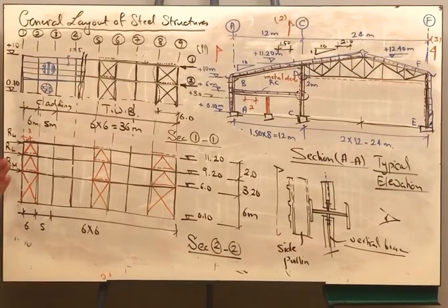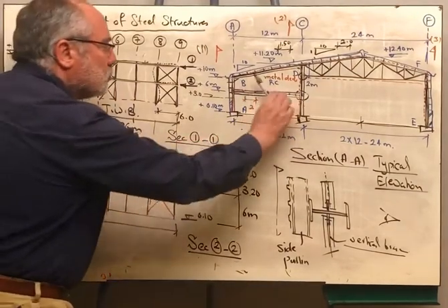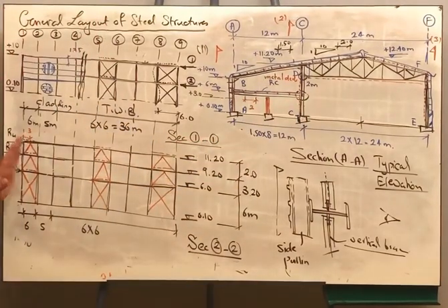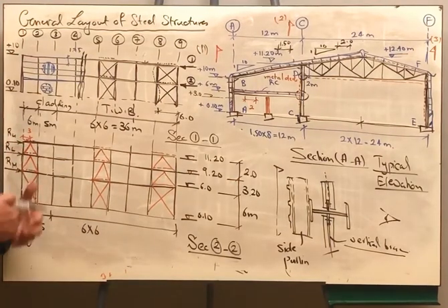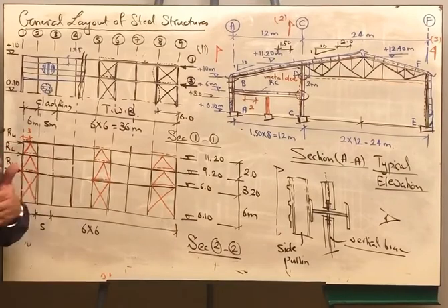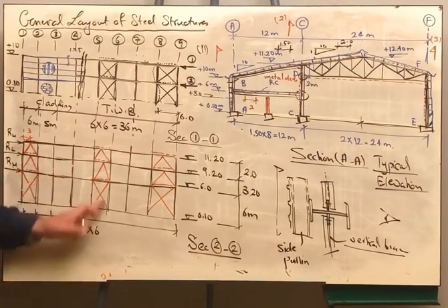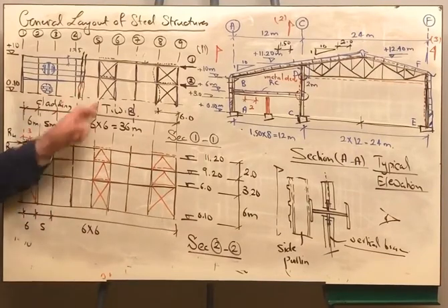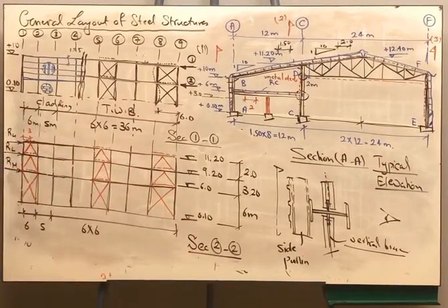And here we don't have cladding because this is the area between the two holes. We don't have a cladding system. The cladding system, for example, is a brick wall or something that does not require the use of purlins. We are just putting our bracing, and the bracing, of course, should be consistent in the same base like that.